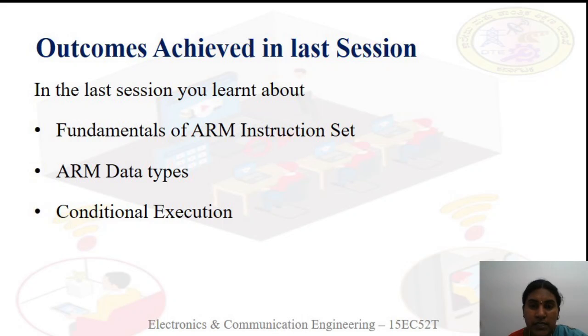Then our ARM instruction always uses load and store architecture. What do you mean by load and store architecture? Our ARM data operating instructions do not manipulate data within a memory. So, to manipulate the data within a memory, first we have to store the data into the memory and retrieve the data again into the register. Then we go for the manipulation. To do all this process, we go for the load and store architecture.